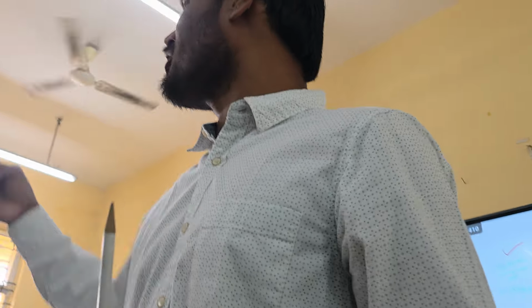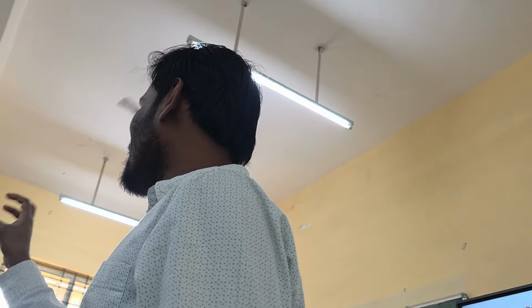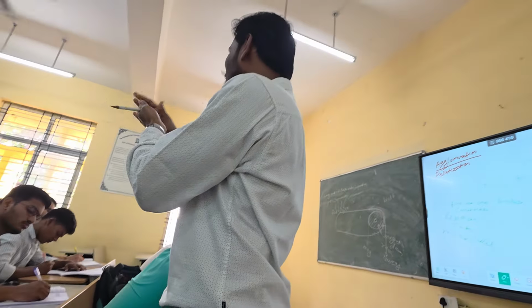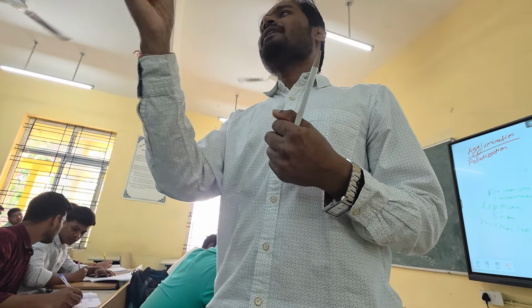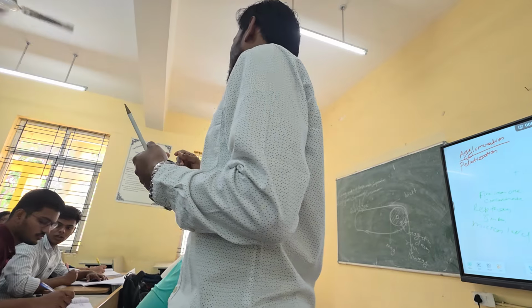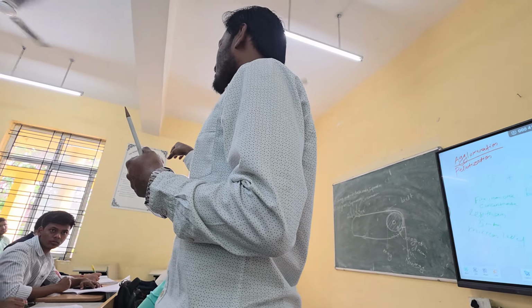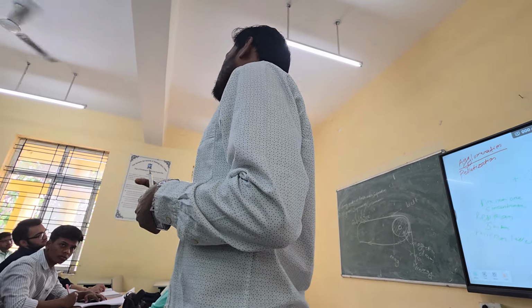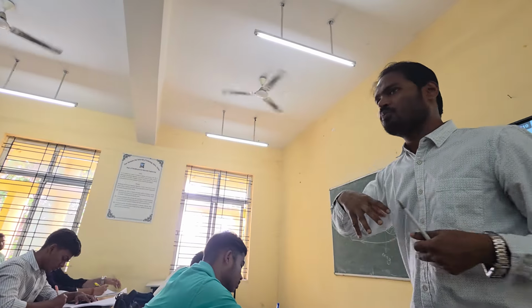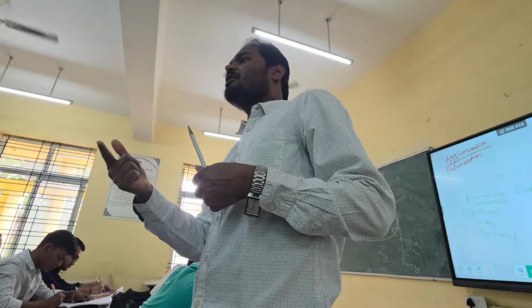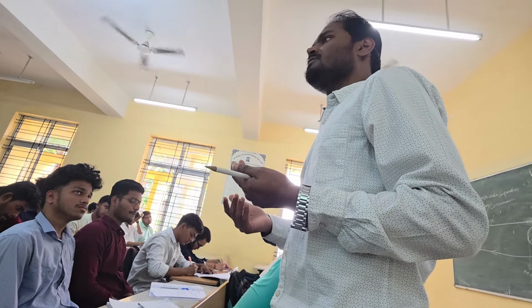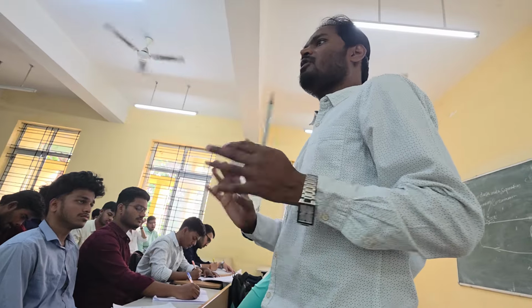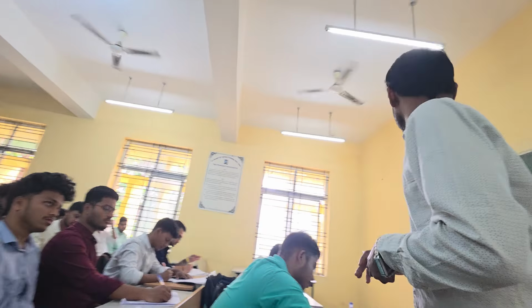If you take soil and put some water and make a ball, a ball can be easily formed, because clay is a sticky material, right? The same clay, bentonite, you can use for binding purposes. You take iron ore and put some in, but the amount of binder used is very small, hardly 1%. Only 1%. The rest will be your iron ore fines or whatever.